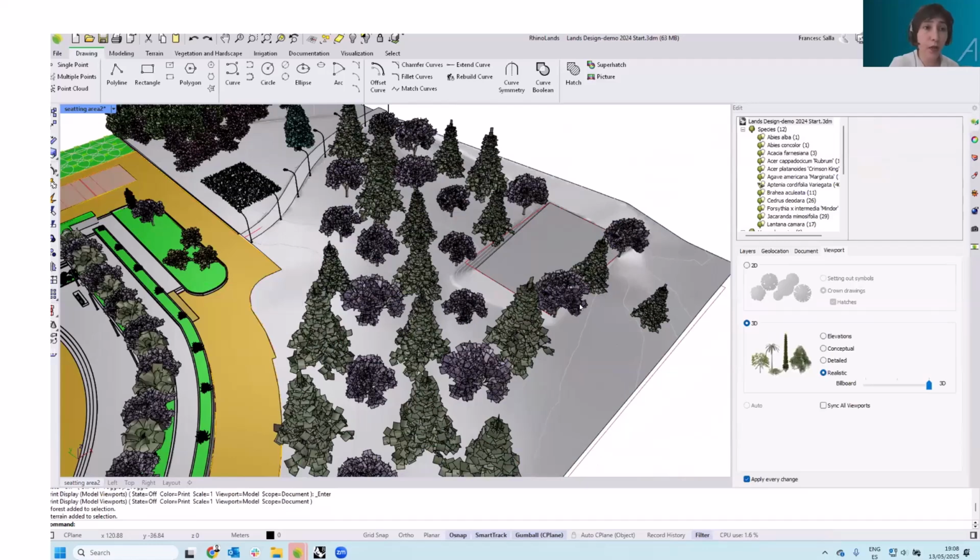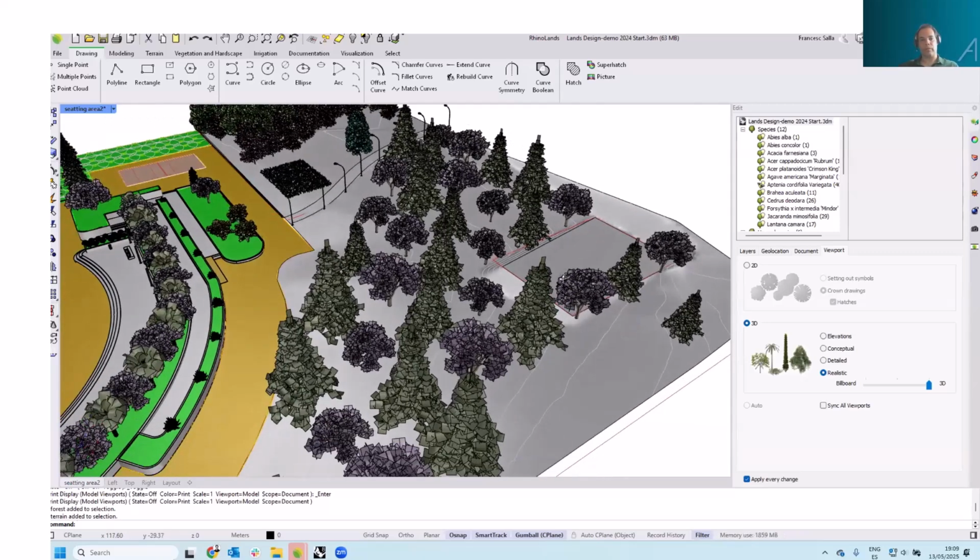But if you are starting from zero and have no topography, first you need to generate the topography or the terrain. Exactly. And there are methods also to calculate the intersection between a terrain and a surface, so you can obtain the contour. With this contour, you can generate a surface, maybe for assigning a water material. So that's the way you could do it.